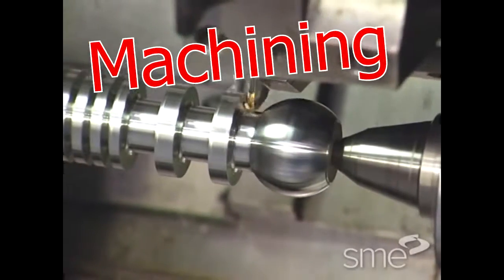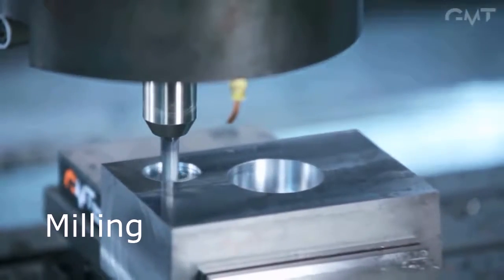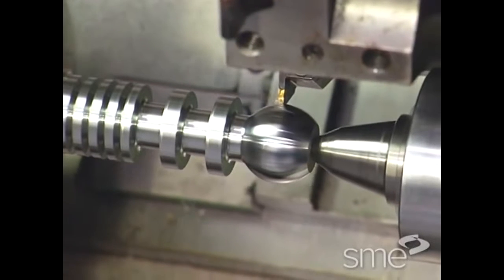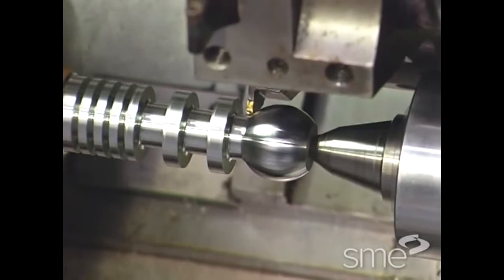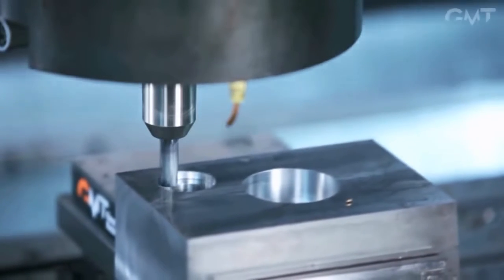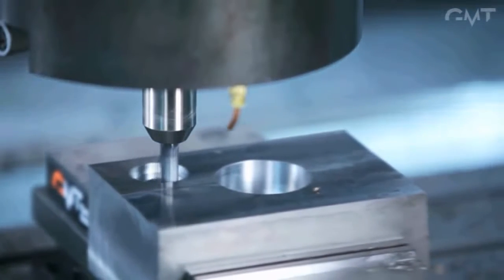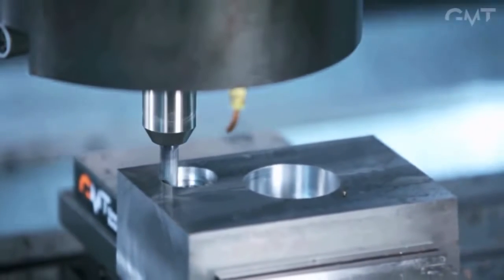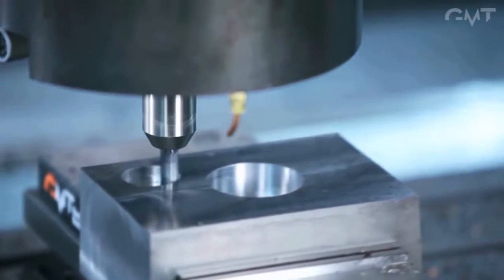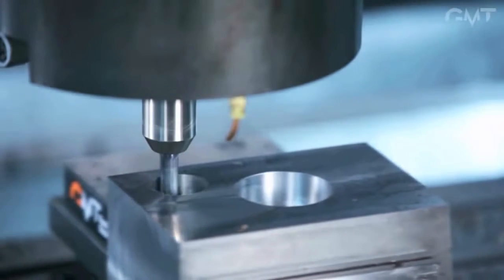Machining is another group of processes that can be divided into two categories: turning and milling. Turning operations rotate a piece of raw material while the user is either in control of or holding a cutting tool that removes material while the piece is being rotated. Milling is the opposite of turning, in that in turning, the workpiece is rotating, and in milling, the cutting tool spins into a stationary workpiece. Drilling can be done by lowering the rotating cutting tool's edges into contact with the workpiece. This can be done on both lathes and milling machines.